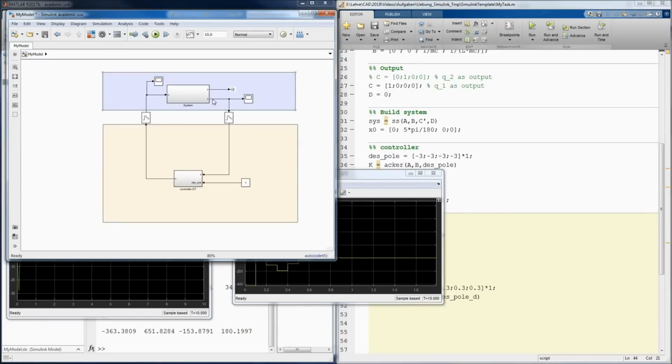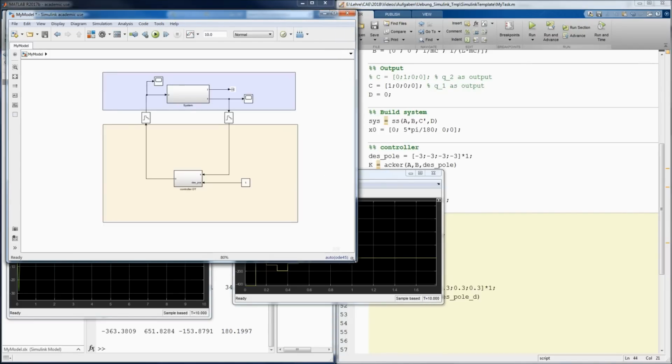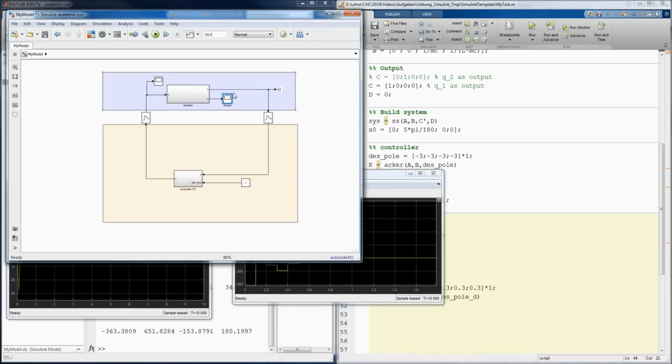So obviously it's a good controller if you have access to all of the states of the system, but in practice that's not always the case. So this means that you somehow need to reconstruct the states, because actually what you have is the output of the system and not the state. So what you do is basically you bring out the output where you have installed your sensors, and the state is actually inside the system but not visible to you.